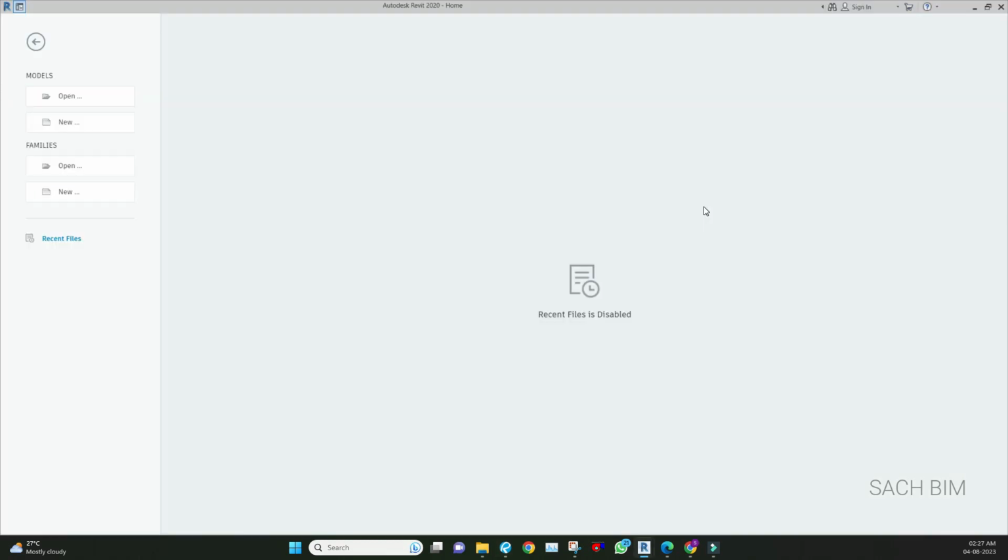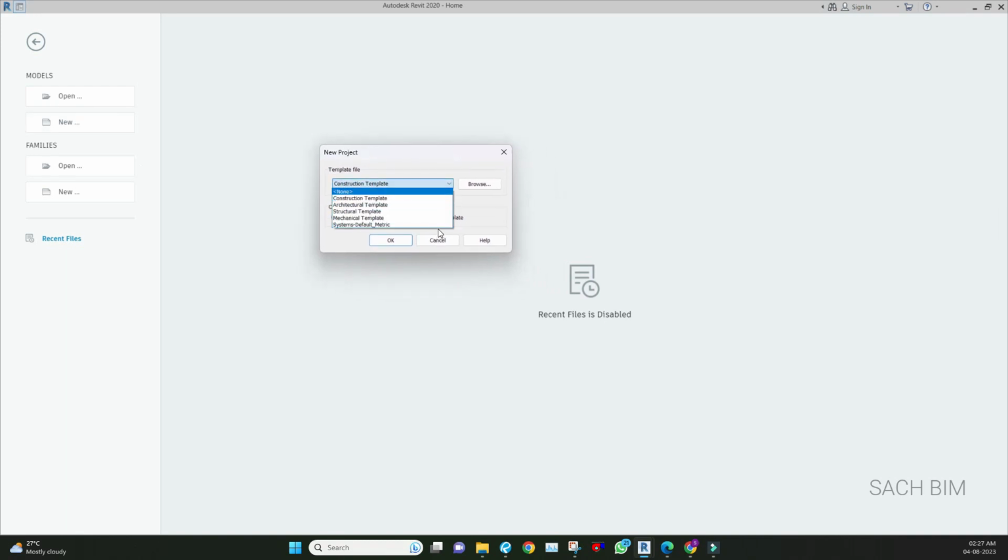So next we are looking into how we can create a new project template. For that, go to Revit, then click new, then an additional pop-up will come. Actually there are two methods. You can create it from scratch or you can modify any of the templates. I will prefer the modifying option. Why? Because why start from zero? So better to go with the modifying option.